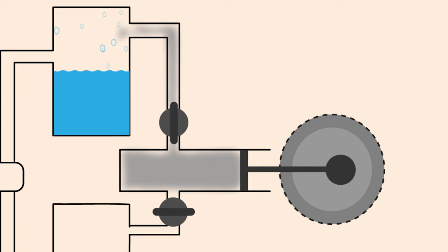As the steam expands in the cylinder, it pushes the piston forward. Crankshaft connected to the piston also moves. Crankshaft converts linear movement of the piston into circular motion. The wheel of the crankshaft makes half rotation during the expansion stroke.